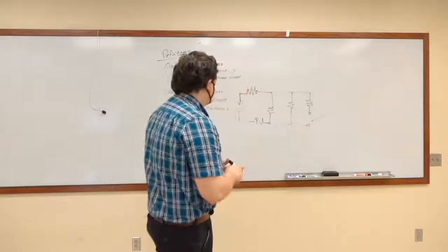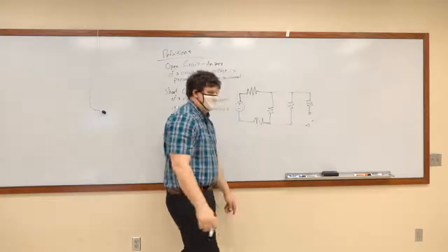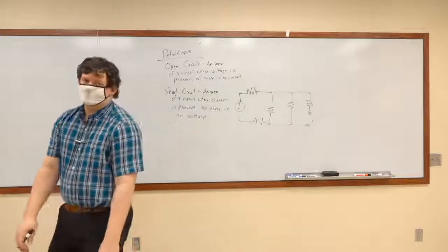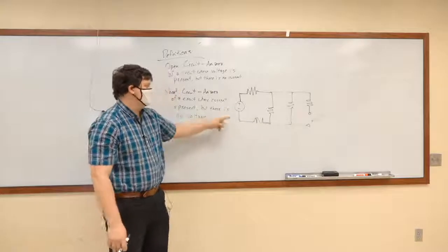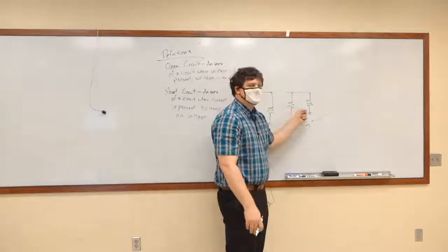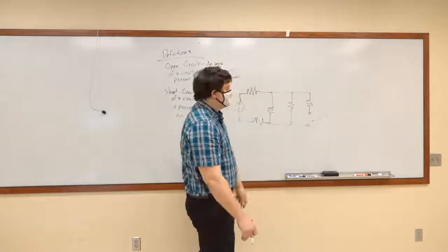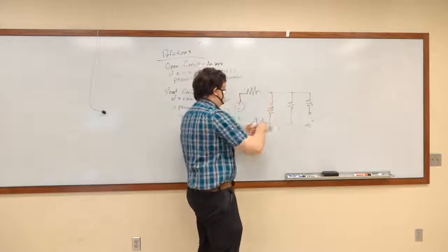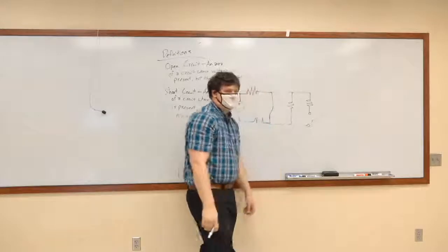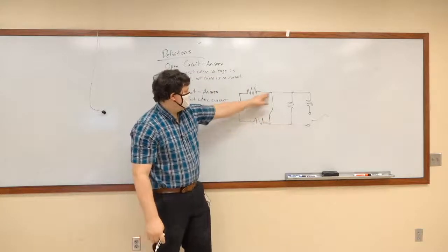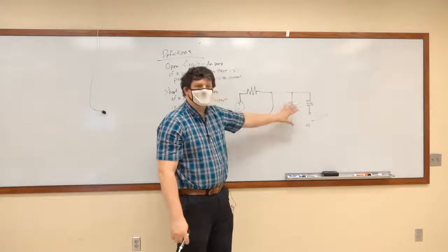So here, in this system, this here is a short circuit because there's no voltage drop across that wire. But there is current present. There's current going through that wire headed here. Now this isn't exactly a short circuit, even though, yeah, it's a wire. There's no current going to be going through that. So that's not going to be a short circuit. You could call this a short circuit. Or you could do this, and that's a short circuit. And now there is no voltage between this terminal and this terminal, this node and this node, which also means there's not going to be current flowing here.